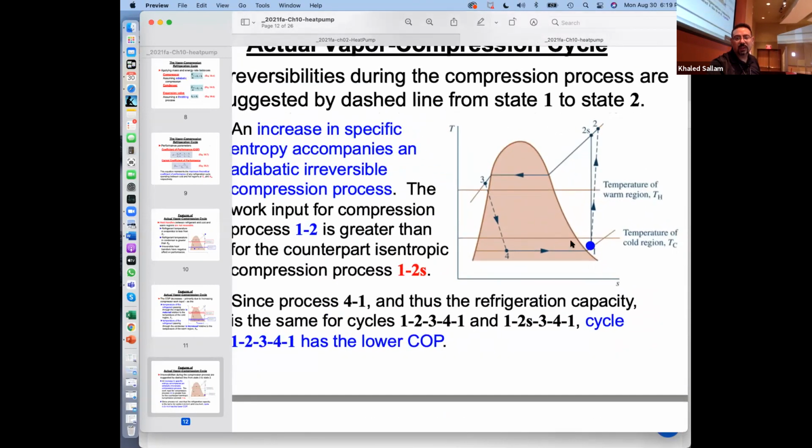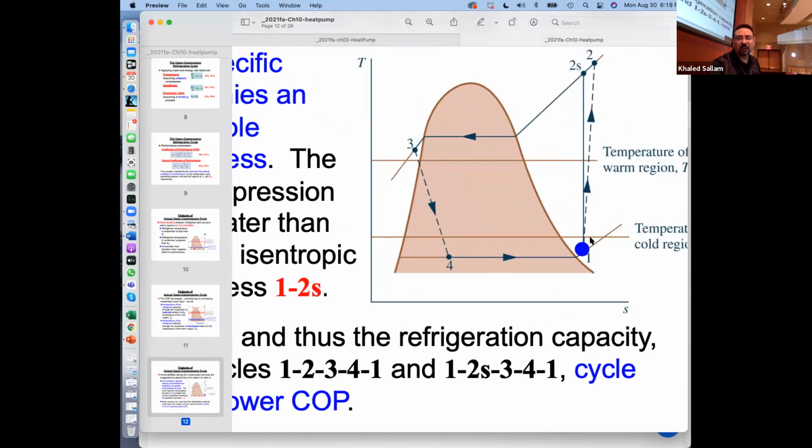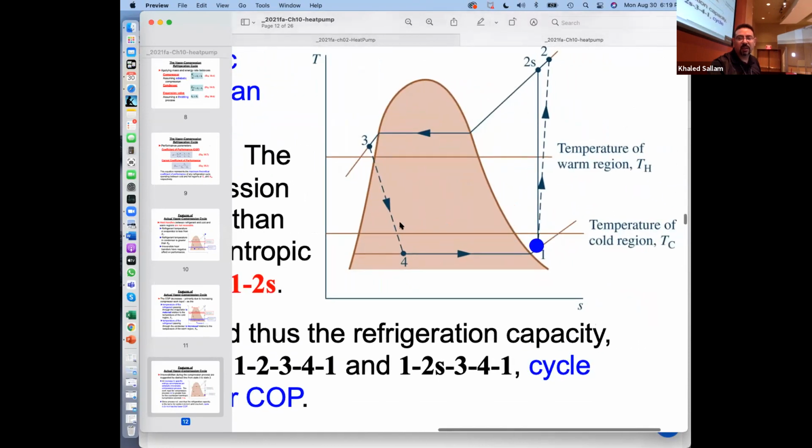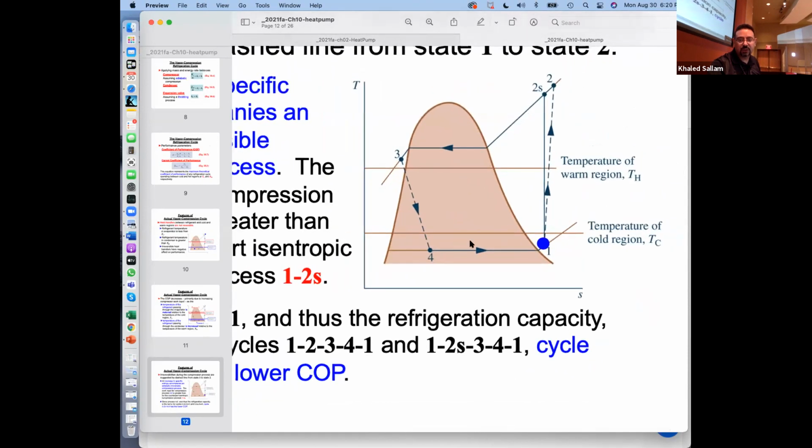The actual cycle will have those features too, right? It can get a little bit superheated. And why would you get a little bit superheated? Because the TC is here. The temperature in the fridge or the room, whatever the cold place you are trying to cool even more, is here, and the refrigerant comes in and boils until it is all saturated vapor.